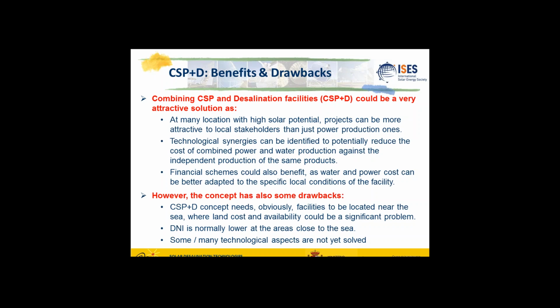So here in this picture you have the typical scheme of a solar thermal parabolic trough plant for production of electricity. And the idea is that, like in a typical thermal fossil fuel plant, from all the thermal energy that we are able to supply from the solar system, let's say the 100%, the typical Rankine efficiency in a typical commercial plant is around 40%.